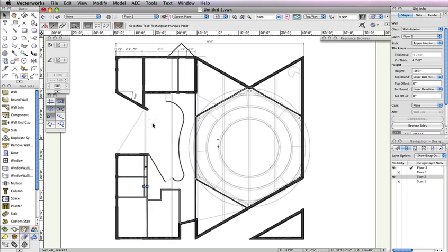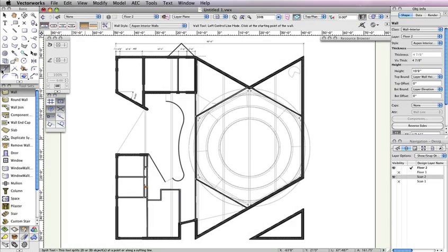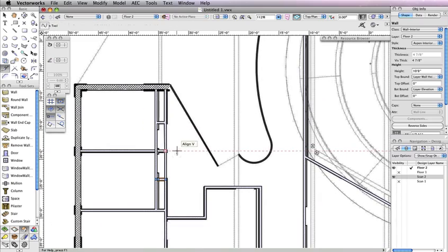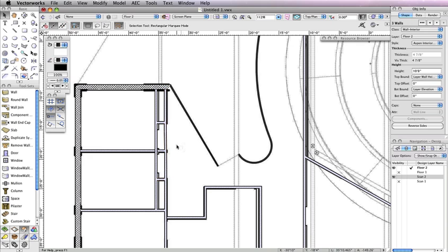For the last set of walls in the lower left rooms, we need to use the Split tool and the Wall Join tool to create openings. First, we'll use the split tool in point split mode. Just click this wall twice, somewhere around these two areas. The wall is now split at these 2 points, leaving the resulting wall still selected. We don't need this portion, so press the delete key to remove it.